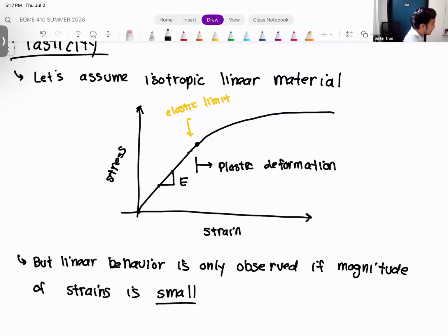Another thing that changes is that if you push past the elastic limit and release the load, releasing the load anywhere within the plastic region is not going to return the structure to its original state. You've probably seen this a million times at this point, but let's say that we stress the structure such that we get our stress strain into that plastic region.